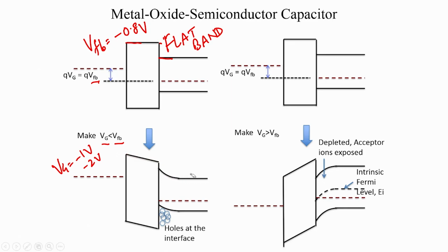And when we start making Vg less than Vfp, this band bending is going to encourage all the majority carriers, since you remember this is a p type semiconductor and it has a lot of holes. So, for example, if it is doped with dopant concentration Na, and if all these dopants are ionized, then the hole concentration is about Na, if Na is much greater than the intrinsic carrier concentration.